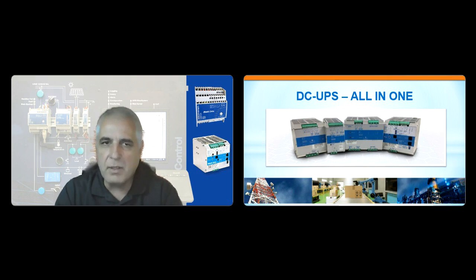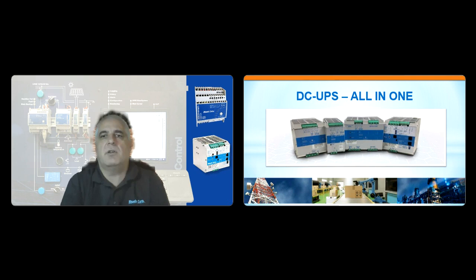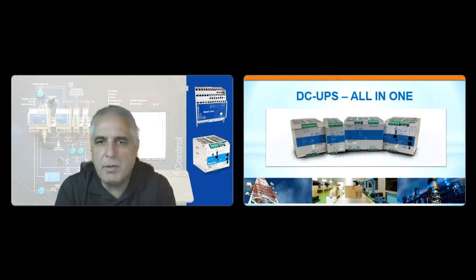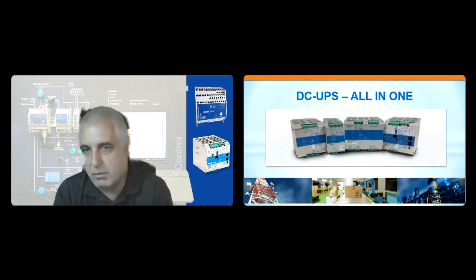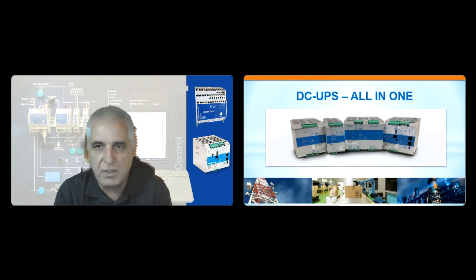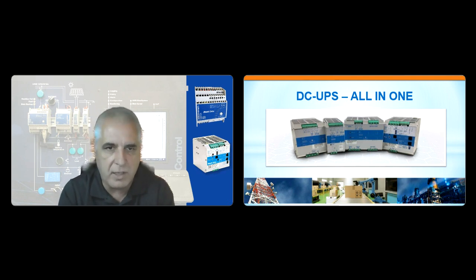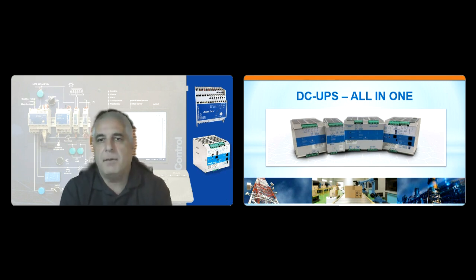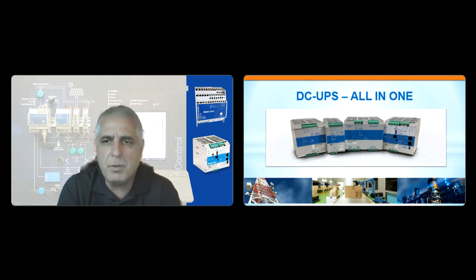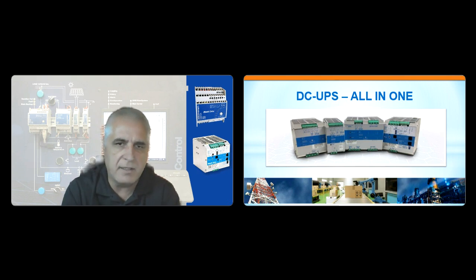The more modern and the most widely used would be a switch mode charger, also known as a switching charger. The switch mode power supply or switch mode battery charger or UPS uses a high frequency switching circuit to regulate the charging voltage and current. And as I mentioned, it's the most common type of battery charger in the market. They are often used in portable electronics devices as well, power tools or electrical vehicles and everything in between.